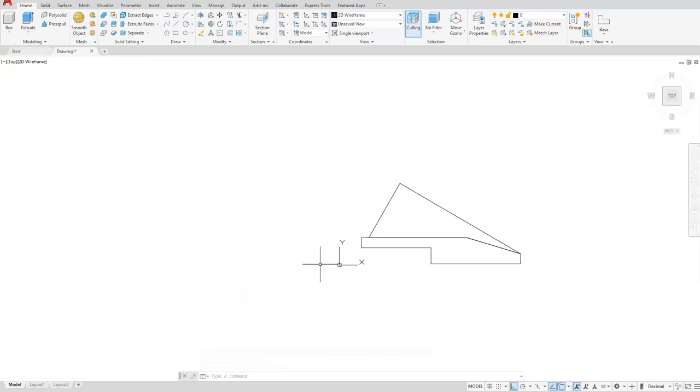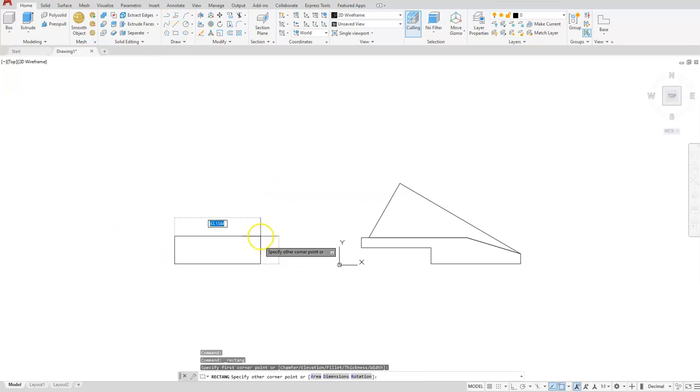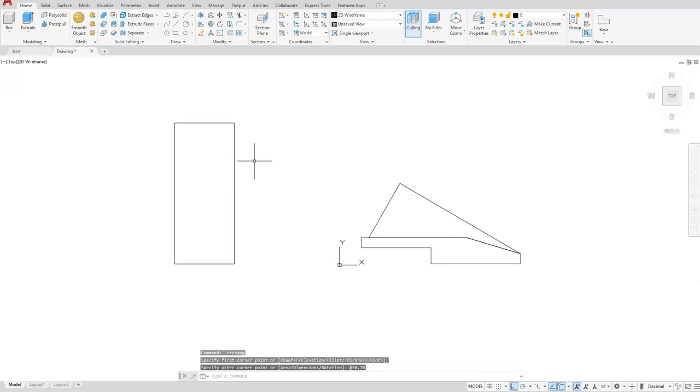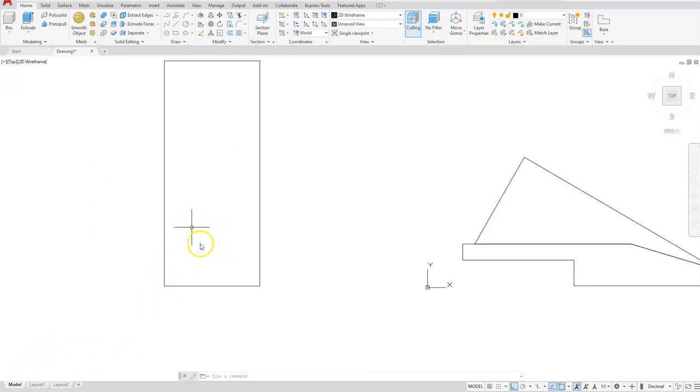Now over here to the side, I'm going to create a sketch that I'm going to use to locate my circles. So I'll create a rectangle. And the other coordinates that I'm going to need from my other corner should be 30, comma 70. My center of my hole is located from this edge, and it's over 5 and up 10.